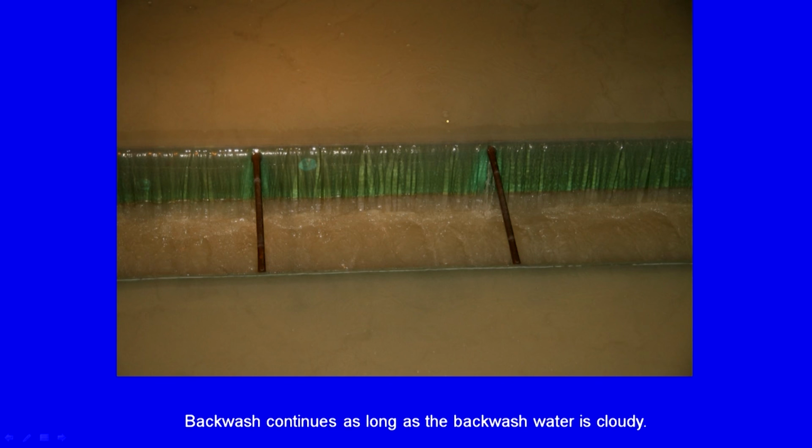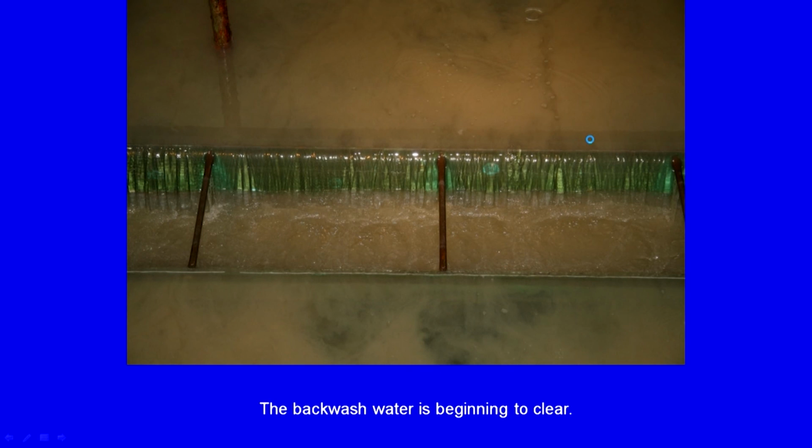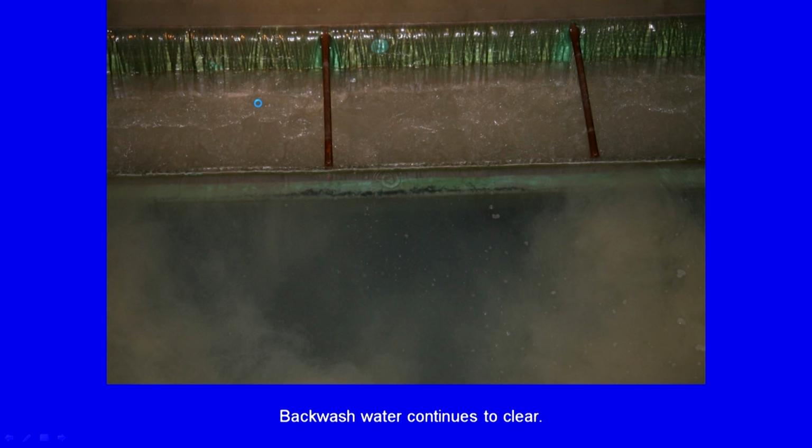And how long will I do that? Well, it depends upon the level of treatment, but one thumb rule is, if you are doing that manually, you can look at how clean the water is, but rarely is that done. So, you can see that it is still cloudy, but after some operation you see that it is relatively clearer. And after some time water is starting to become relatively clearer. And again, after more continuous backwashing, the backwash water is starting to become clearer, meaning the filter is relatively cleaner now.